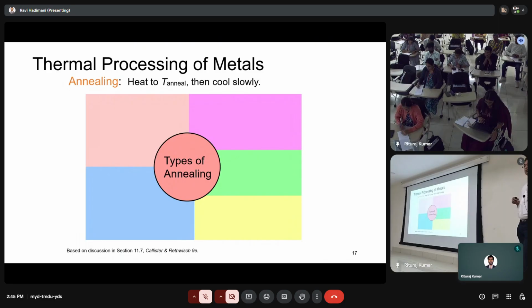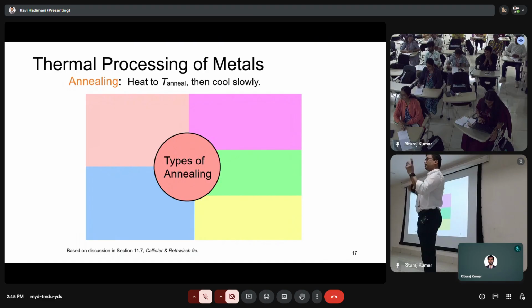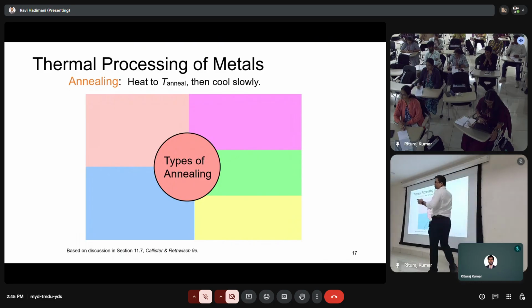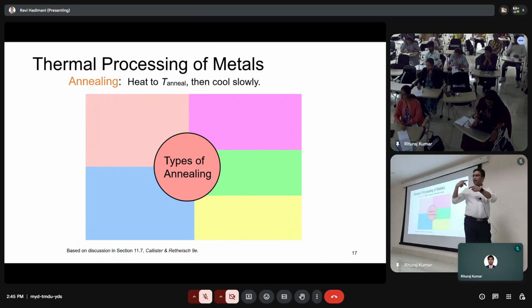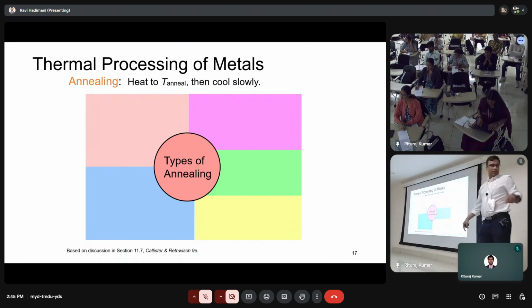So annealing reduces the dislocation density because you give enough thermal energy for the dislocations to move, and opposite dislocations. Dislocations can be clockwise vector dislocation and counterclockwise vector dislocation. And when clockwise and counterclockwise dislocations meet, they annihilate. So when you increase the temperature, you're basically giving thermal energy and the dislocations move around. And when a counterclockwise meets with the clockwise dislocation, they annihilate. Okay, that's how by annealing you are reducing the dislocation density.